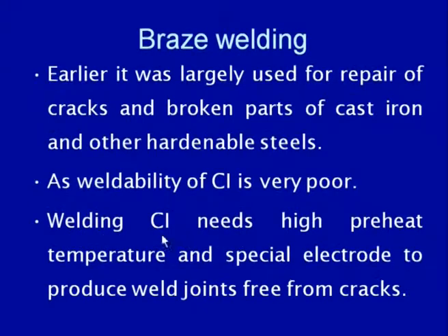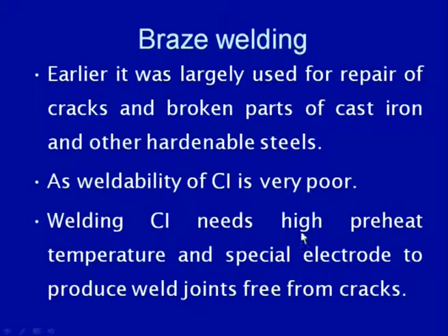So, if we try to weld the cast iron, it requires a high preheating temperature, which is difficult to work with, because a high preheat temperature imposes many difficulties on the operator during the welding process. Due to the high temperature, the handling of the workpiece and the application of the welding becomes difficult, and that is why the welding of the cast iron using high temperature is difficult.